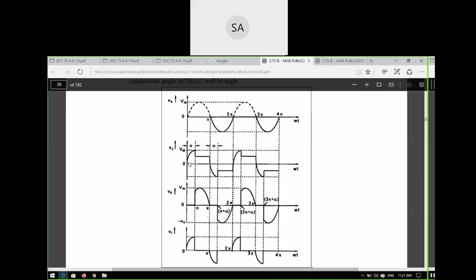Okay. So whenever the capacitor is charged, a pulse is generated at the triac. So the triggering pulse is generated here. You can see here, the charging time increases and the same appears at the triac. VT is the triggering pulse, or the voltage at the triac. So whenever it is triggered on, then it is the conduction angle. You have alpha. So after alpha, the output voltage will rise. That will be conduction. So that is the reason it is a conduction angle. So what is the conduction angle? Pi minus alpha, or 180 minus alpha.